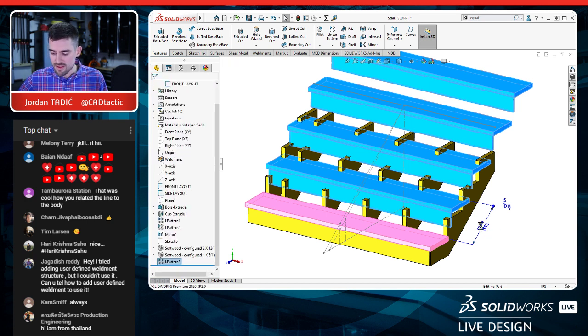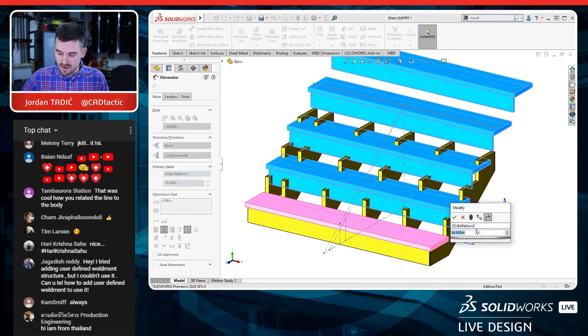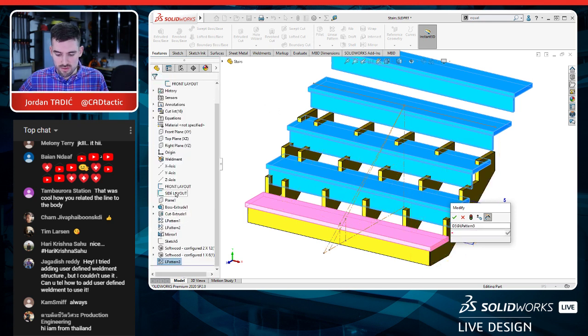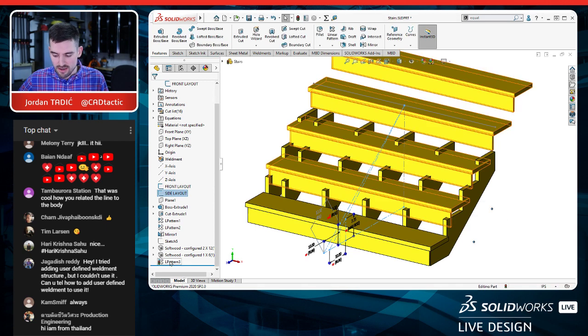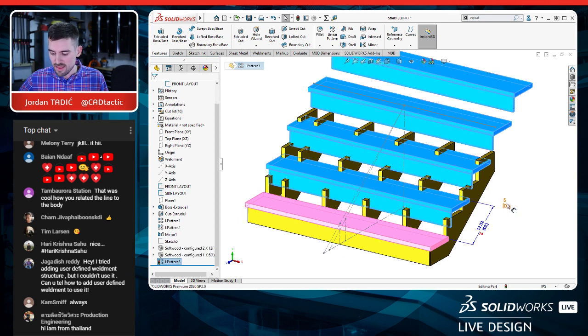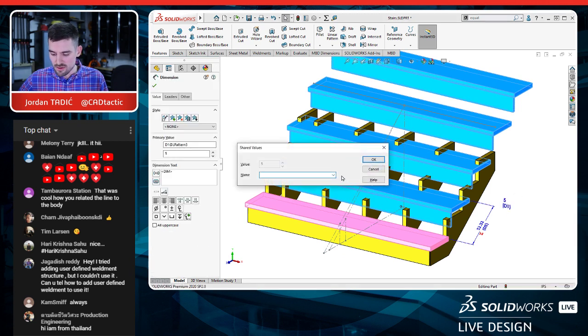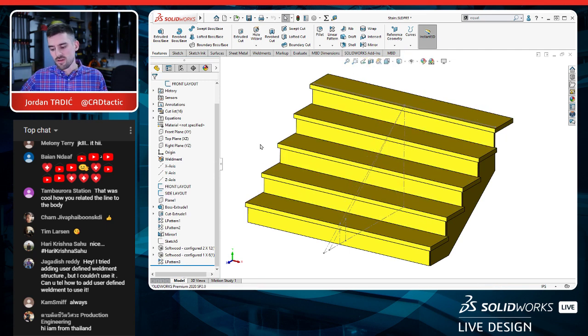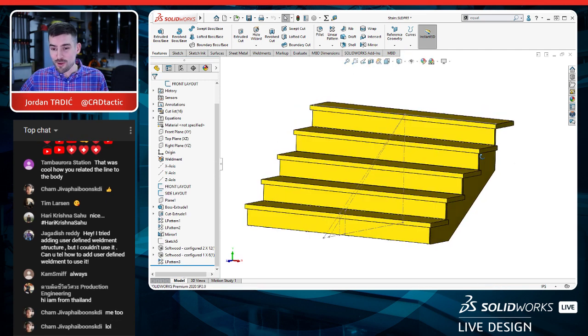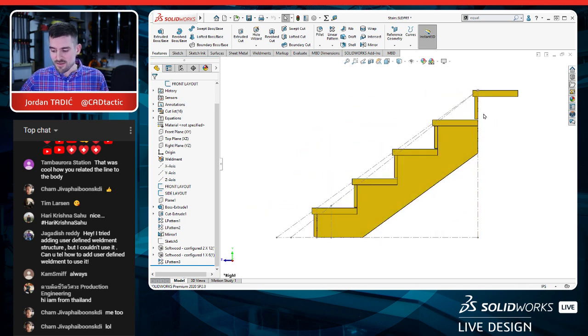I'm going to double-click on the spacing and make that equal to, what? I need to show the side sketch again and make it equal to that dimension. There we go. So second time we've been able to use that. Not a bad idea. And then for the quantity, if I select that linear pattern again, I could right-click that and link that to nothing else than the stair quantity. And hit Control Q, and everything updates.